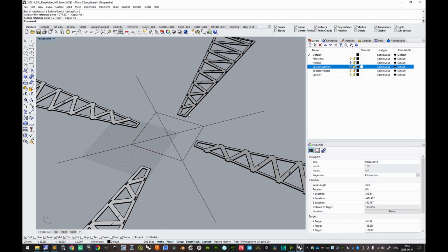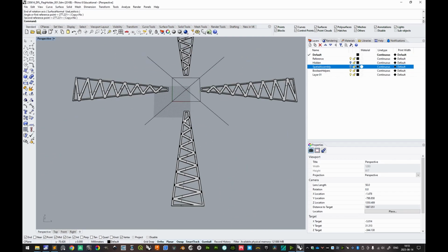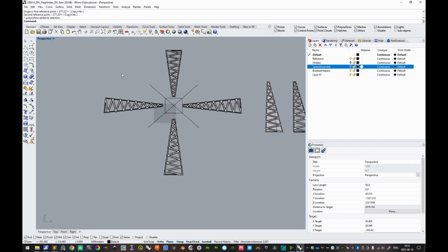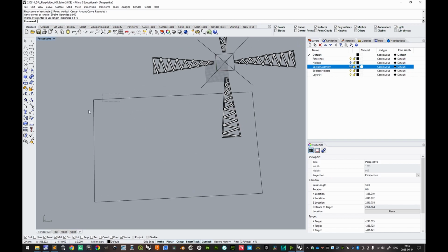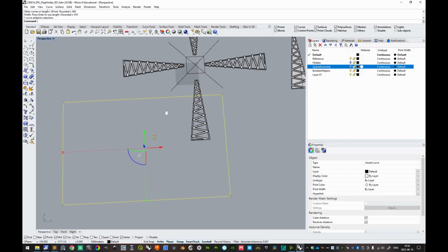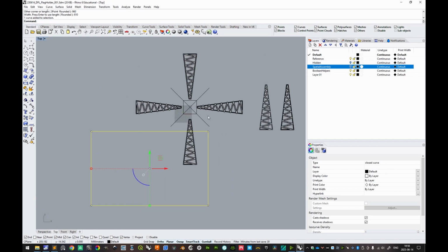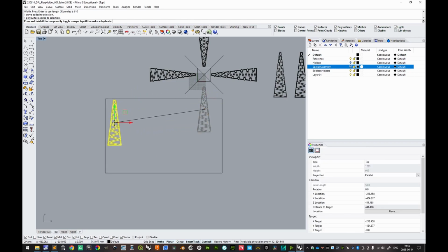All right. With this position flat, we can also make it a little more rational for the laser cutter. The laser cutter has a work area of, we can do a rectangle with an arbitrary starting point here, 960 times 610. So this is the work area of the laser cutter. Now we can work in the 2D top view viewport, and position these any way we want, perhaps like this.